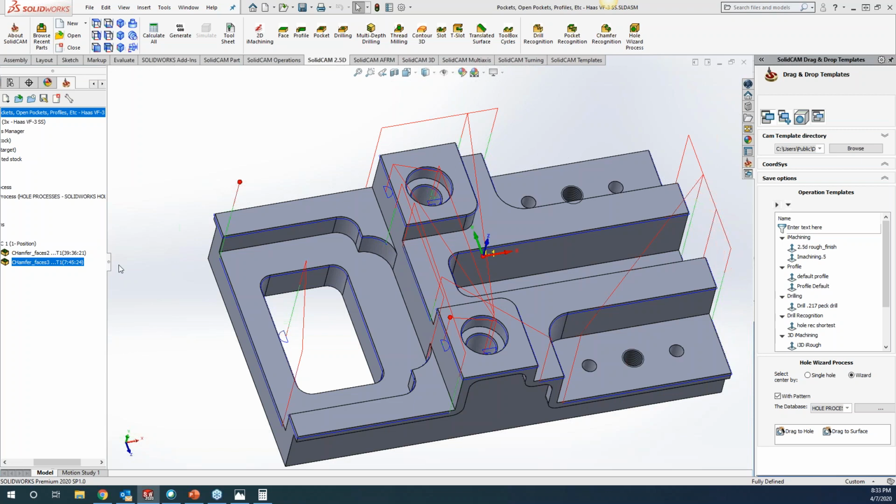Go ahead. Oh, go ahead. I didn't mean to interrupt you, Kevin, but I was just saying this would have been a nice feature to have when I was working in a shop, because we would get some parts out of some carbon steel that were flame cut, that those edges were hard in the pockets that we flame cut, but the rest of it that we can attack in a climb cutting manner, we would. But there were certain pockets that were flame cut, we'd have to come in and conventional cut, and this would have made life a lot easier.